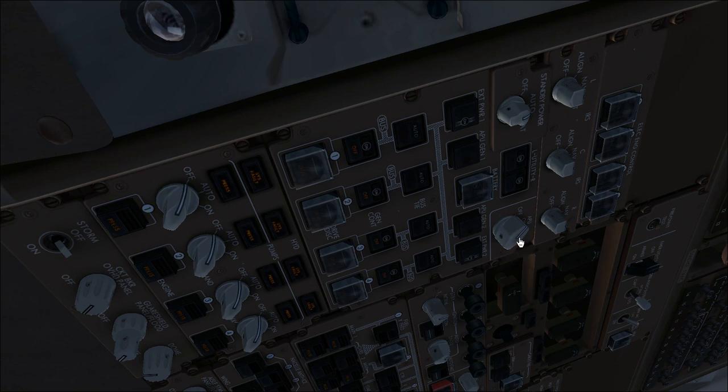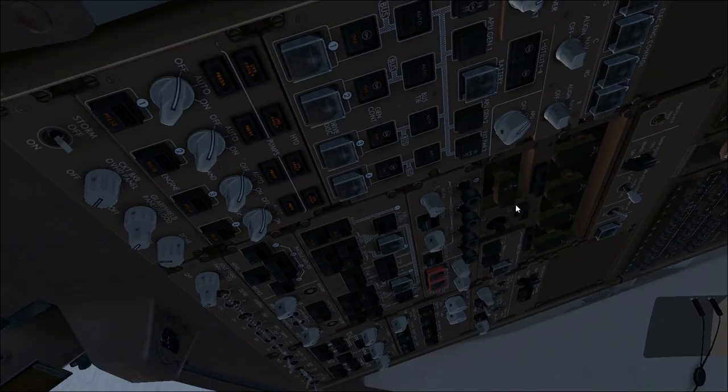As you can see, the APU switch is here. We have off, on and start position, and this is spring loaded to on. We can so select the start position. As you can see, the main two aft pump and main three aft pump are actually losing the pressure light, just because the two tanks actually have DC pumps that power the APU feed line, and these are actually put into the main two aft tank.